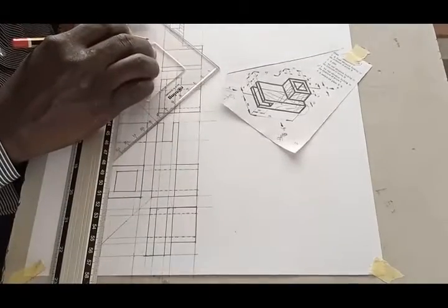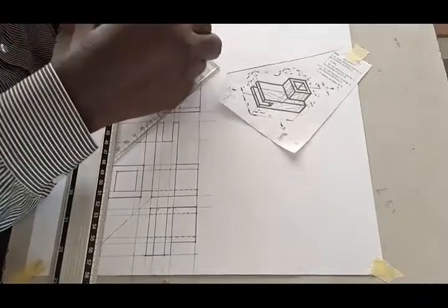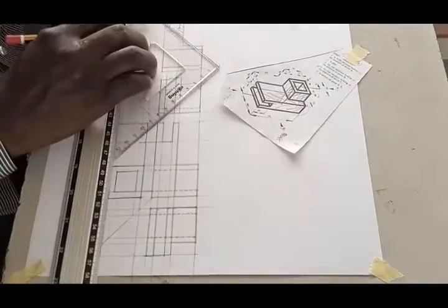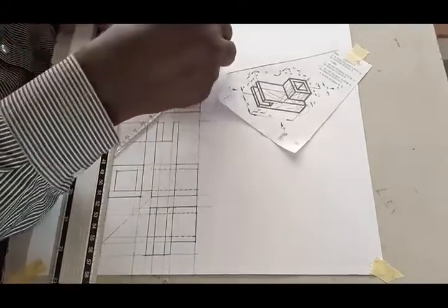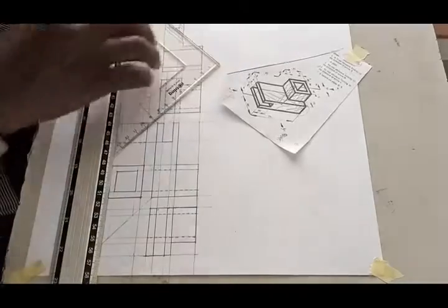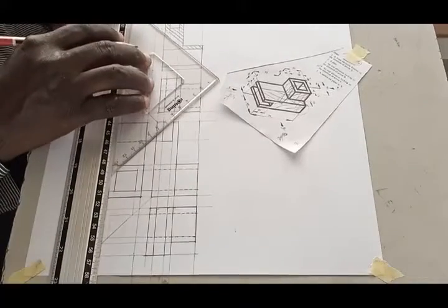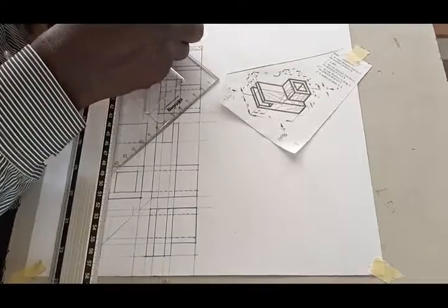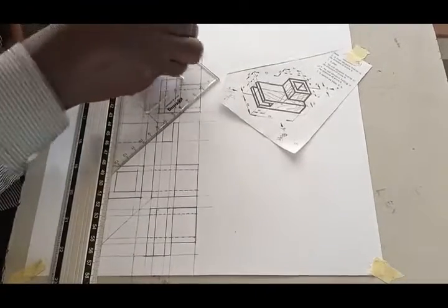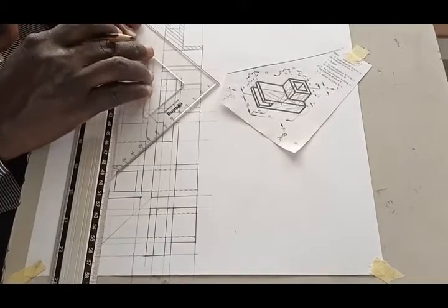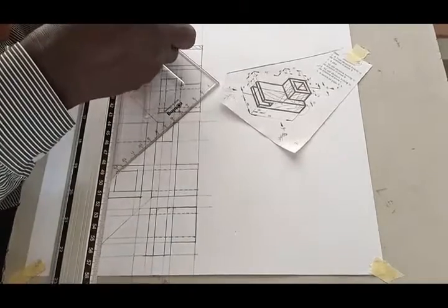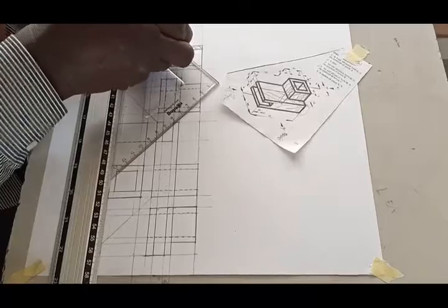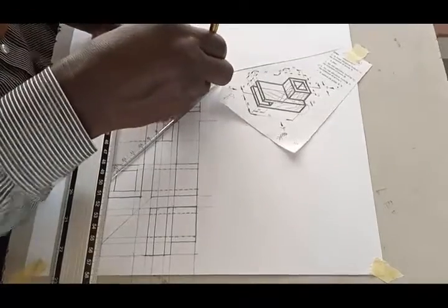And when you are sectioning, you section in the same direction, except you are told that the material or that the object has different materials. That's when you can section in different direction. Or if you are not told that they are of different materials, you assume they are of the same material and you section in the same direction.